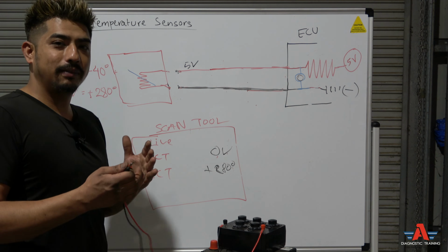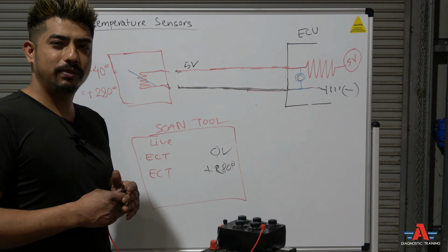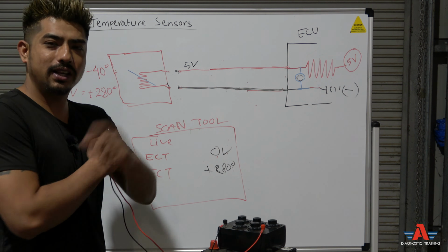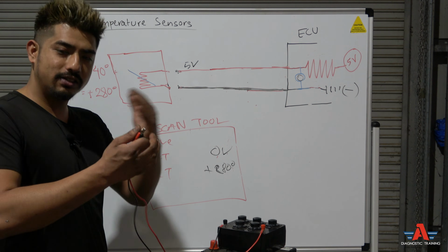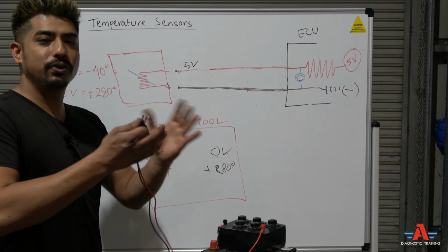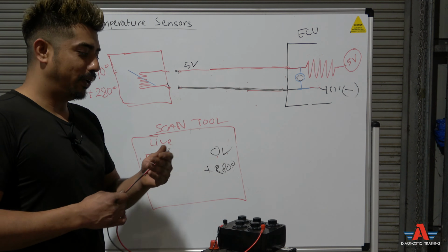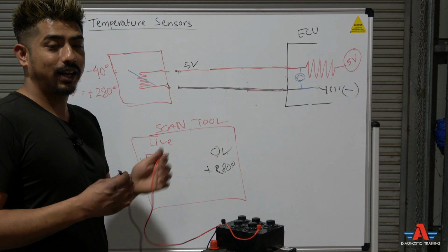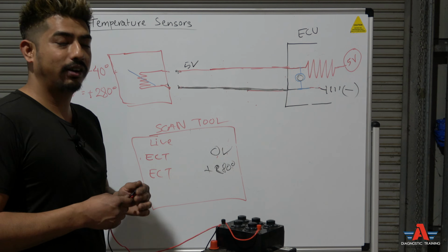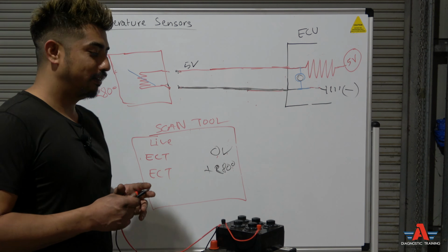As soon as it heats up, 30 seconds, 1 minute, the oxygen sensor is hot and coolant temperatures start climbing. As soon as that happens, the computer corrects the extra air going into the engine from the vacuum leak, so you hear no more hunting. So when I did that, the computer decided, okay, the engine is cold, I'm not going to correct the fuel trim. Maybe that's what happened. This is my understanding.